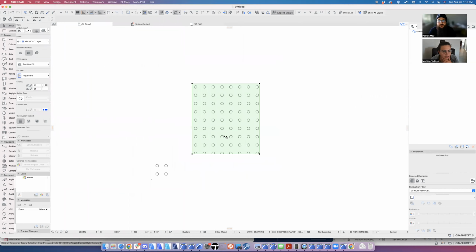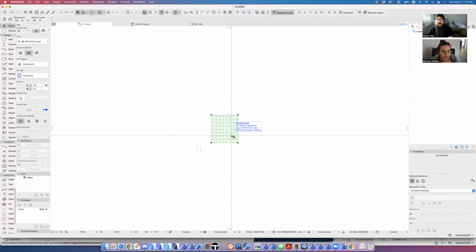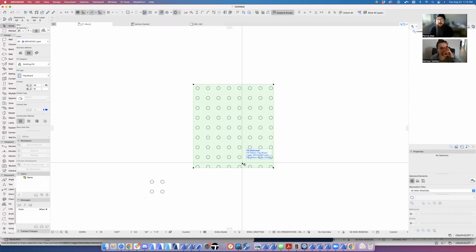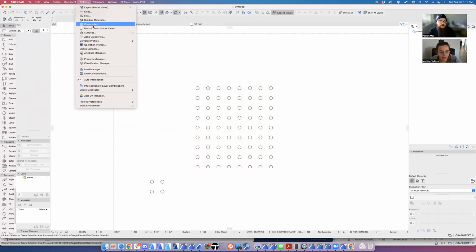Gotcha. You could take it a step further and actually make it show as part of the model, so you're not drafting things over the interior elevation, which is always preferred. The less 2D drafting you're trying to coordinate. You can imagine, if this is behind a cabinet and suddenly the cabinet gets wider, but your fill is overlapping the cabinet, you end up with all that kind of headache. So what you do is you take it to your surfaces,